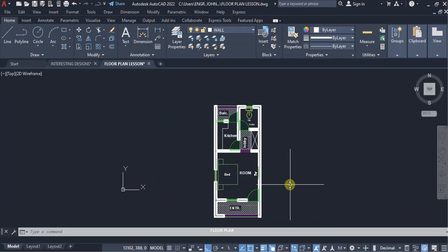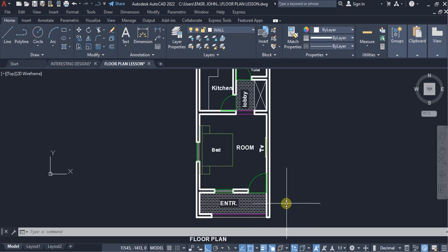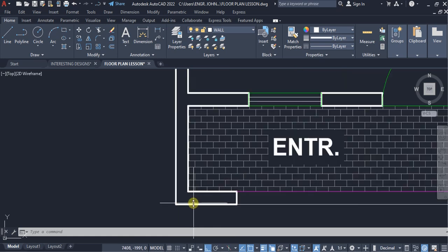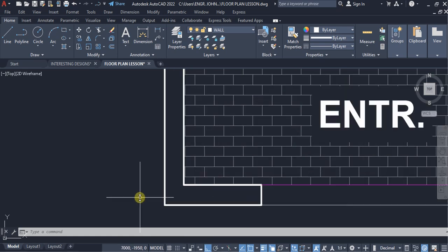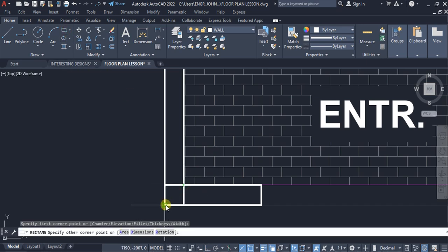Up next is to dimension this, and just before the dimensioning, it's always important to note that grid lines are important, because there are some builders that will not be able to set a building out without grid lines. So for the grids, that's where the construction lines come in handy. Just before I select the construction lines to show you, all I'm going to do now to ascertain the center point of the block walls, I'm just going to pick rectangle and then create something like this.